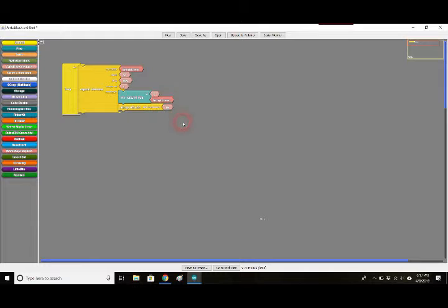I have a delay here of about 10 milliseconds, so it will spend 10 milliseconds at the brightness of 20, and then 10 at the brightness of 21, etc. In our curriculum, I believe I have this number as 100, and that was just kind of a random number I picked after doing this particular project, wiring together this particular LED art. I found that I could dip that number a little bit lower, down all the way to 20, and still get the LED to respond.